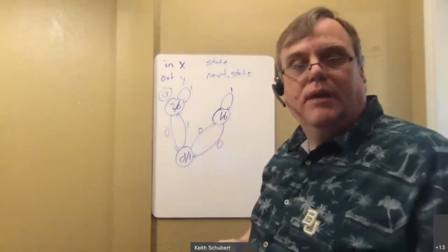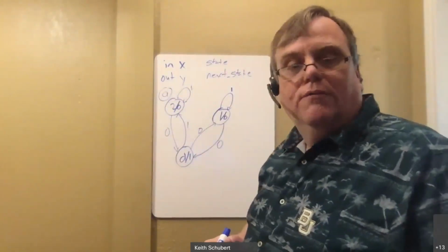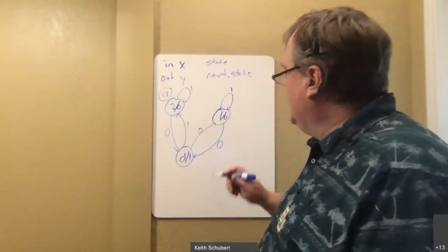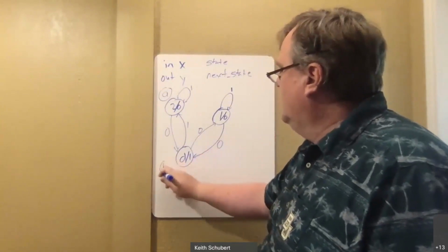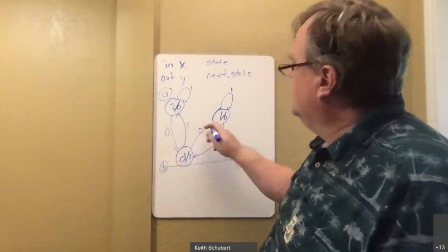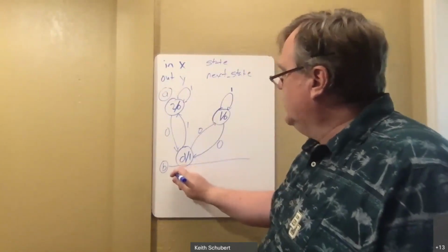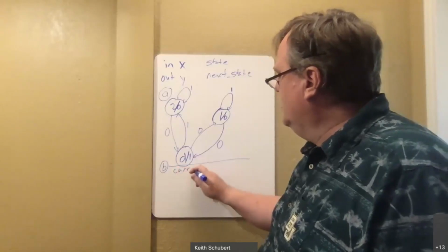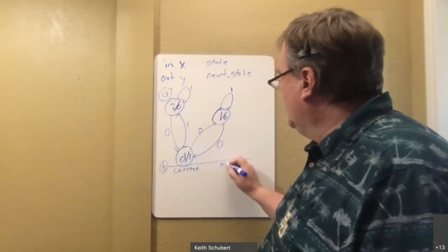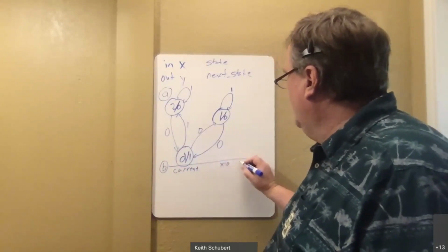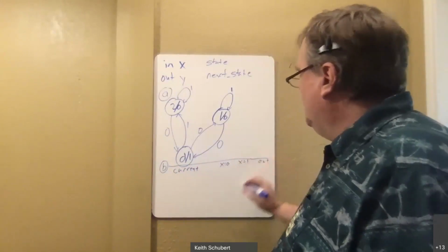All right. Make a state diagram. Boom. There's your state diagram for this. Making a state table is also nice and straightforward. So I'm going to use this diagram to help me make my state table. In a state table, you have your current state, and then you usually have where it goes to if x is equal to 0 and if x is equal to 1, and then we usually have our output.